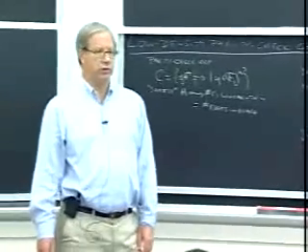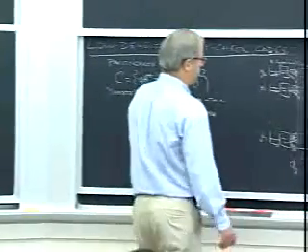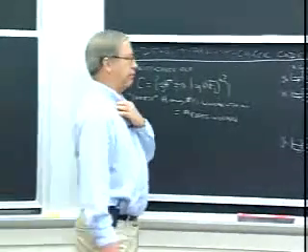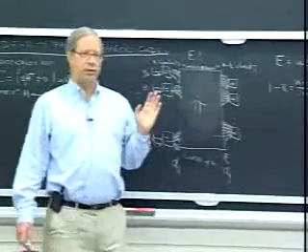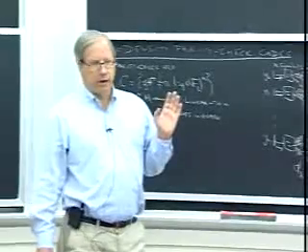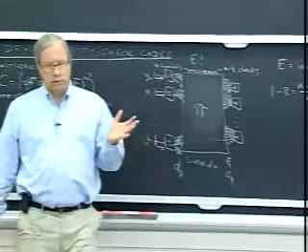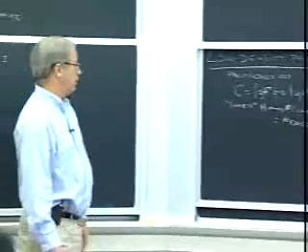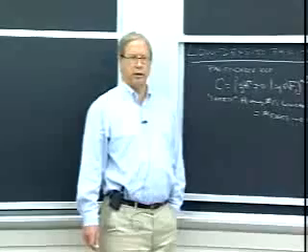So if there's very little noise to start with, this can happen very quickly and terminate the calculation well short. Or you have some maximum number of iterations you're going to allow yourself. If you go 200 iterations and these things still don't check, probably you would say, I've detected a decoding error. One characteristic of low-density parity check codes is they tend to have good minimum distance. They tend to have a minimum distance that's sort of what you would get in a random-like code, which goes up linearly with the block length.